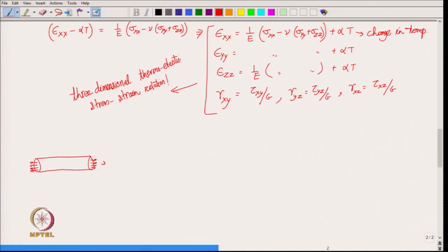So, the stress applied is sigma and the longitudinal strain is epsilon, and if we plot the stress versus strain diagram, then initially it is a straight line, which is the regime of linear stress strain relationship that we covered in this course, and then it becomes curved. This part where it gets curved is the regime of non-linear stress strain relation, because the slope is changing now.